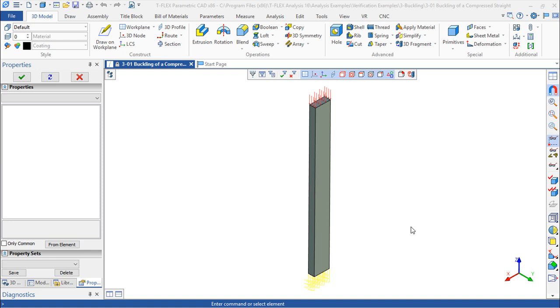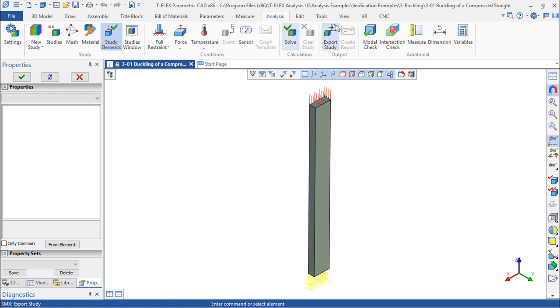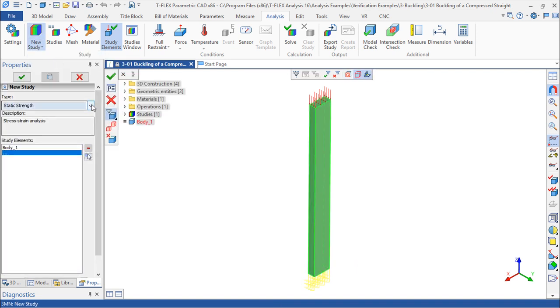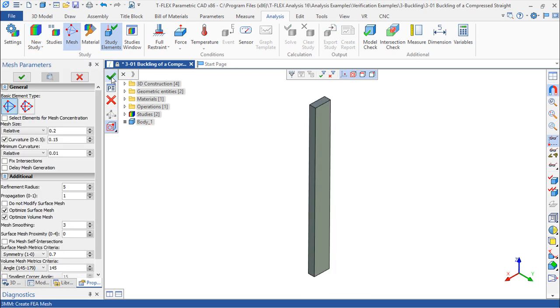So buckling has, as the other calculations, also several stages or steps, what we may call it. The order of steps, in terms of the user, is to put together a study and to run calculations of this buckling analysis. The first one is to create the study. So when we go to analysis, and I've opened one of the examples that the software brings installed, the first thing is to create a study. We can choose buckling. Okay, we accept this. So we've created the study.